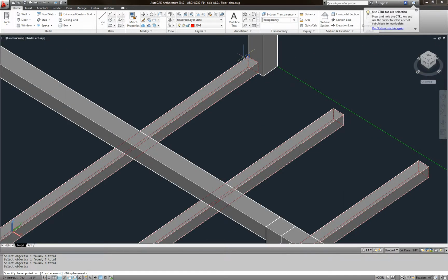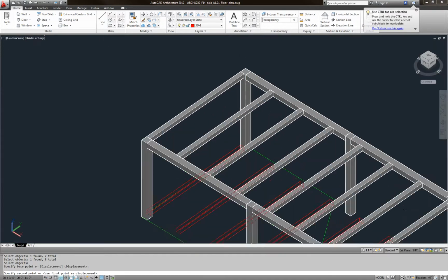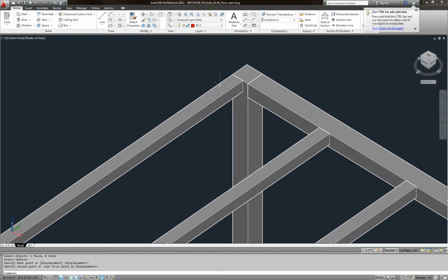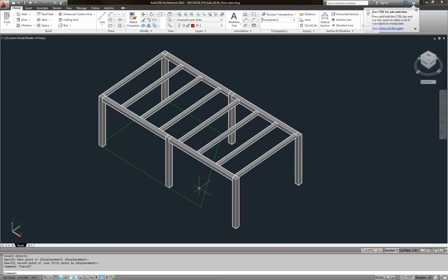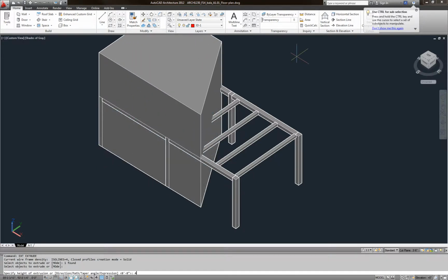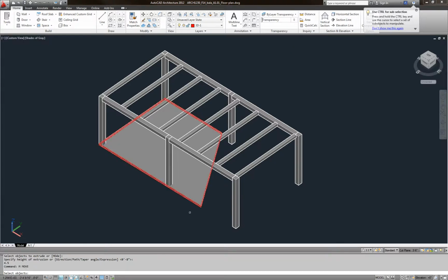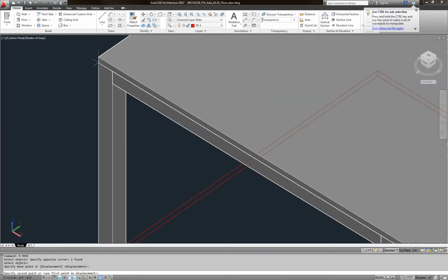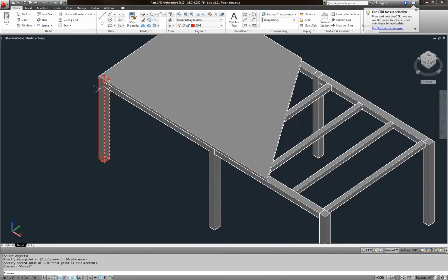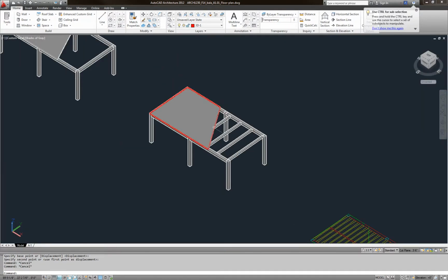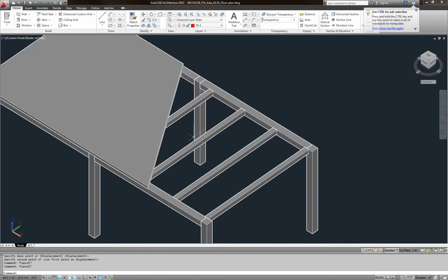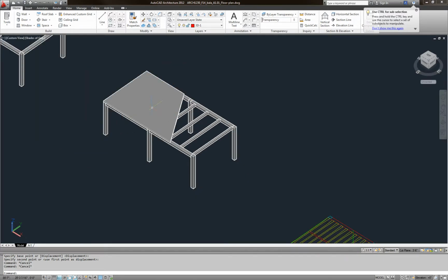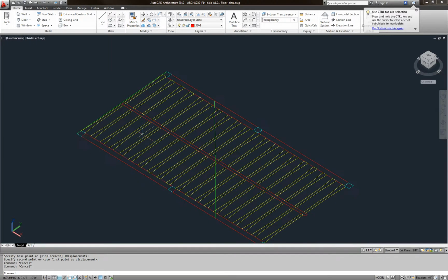I'll go to this corner here. I'm going to go up here to that corner. Okay guys, then I'm going to extrude again. This is going to be 4.5. Move, click the bottom corner, go to the top, and that's it. So you can see the cut here. Instead of putting the whole thing and covering it up, you could have the cut here too. And let's do the same thing for this guy. It's going to look beautiful.